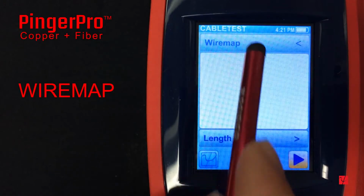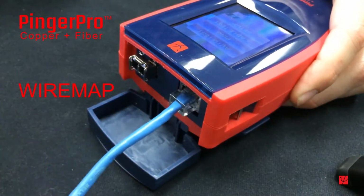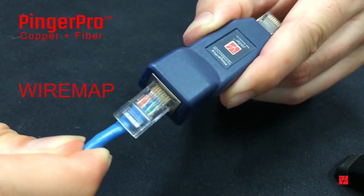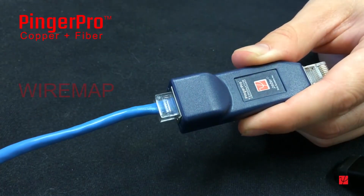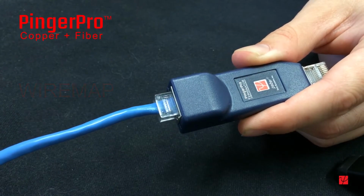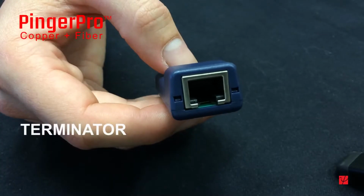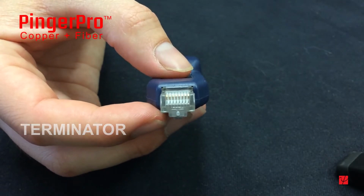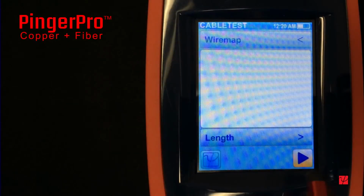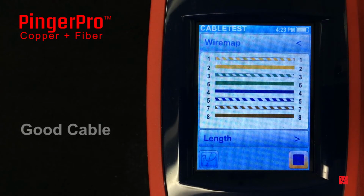Select the wire map test and plug one end of the cable into the PingerPro and the other end into the wire map terminator that comes supplied with the PingerPro. The wire map test will not work unless the wire map terminator is attached to the far end of the cable under test. The PingerPro terminator is designed with a female jack for testing cables with an RJ45 connector and a male RJ45 plug for testing cables connected to a wall outlet. Pressing the play button will begin the test. This is the wire map of a good cable.